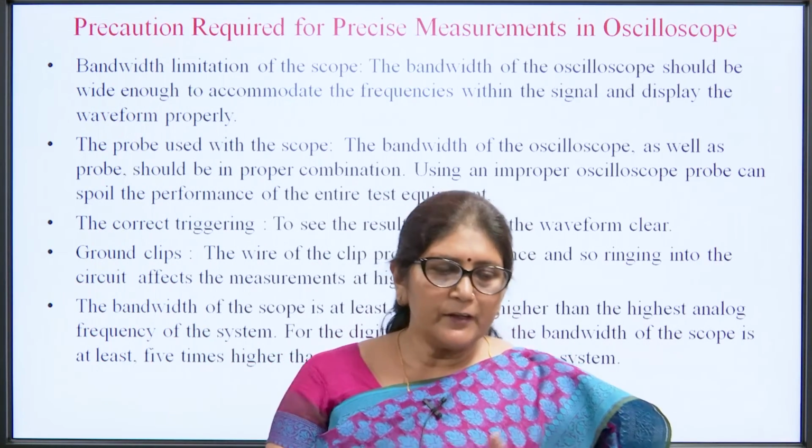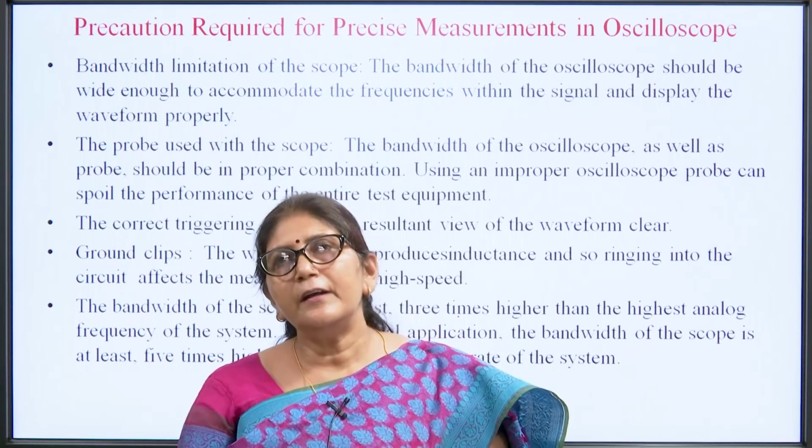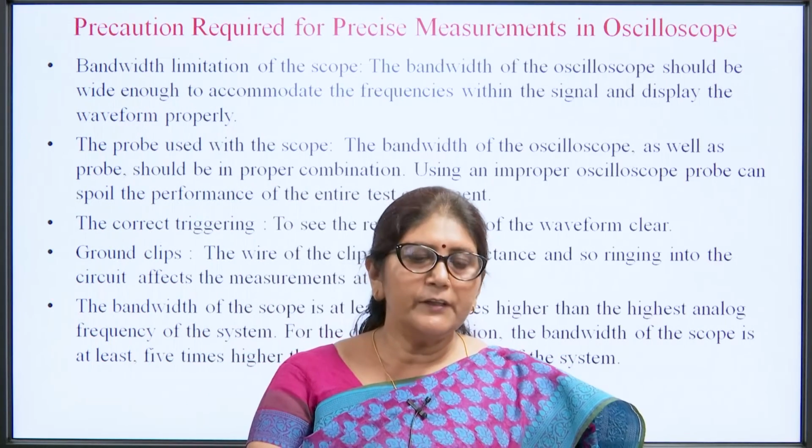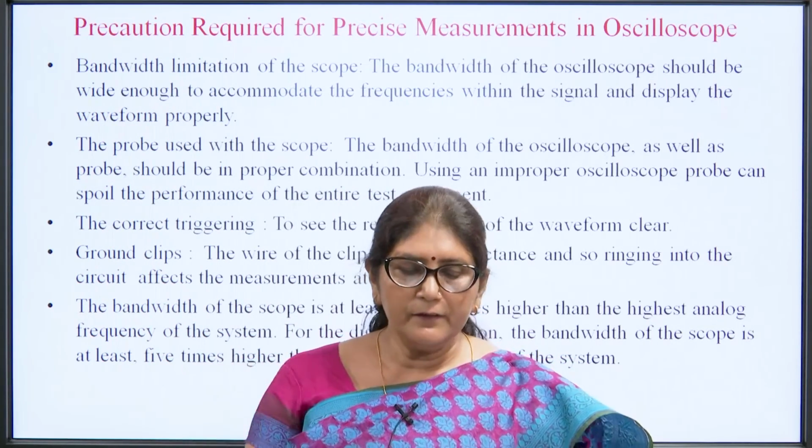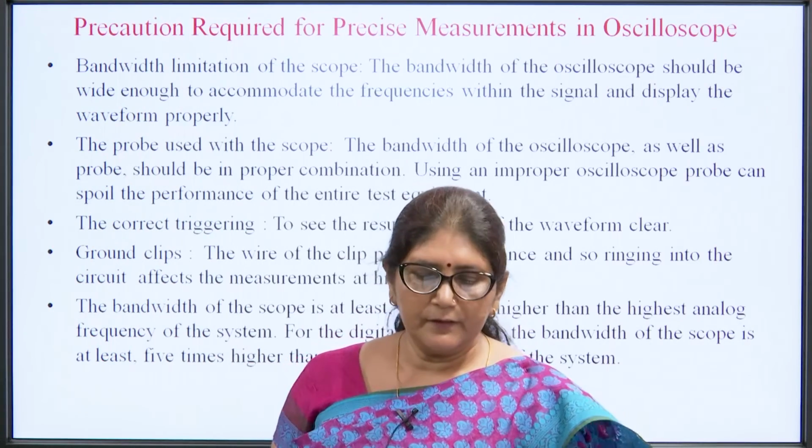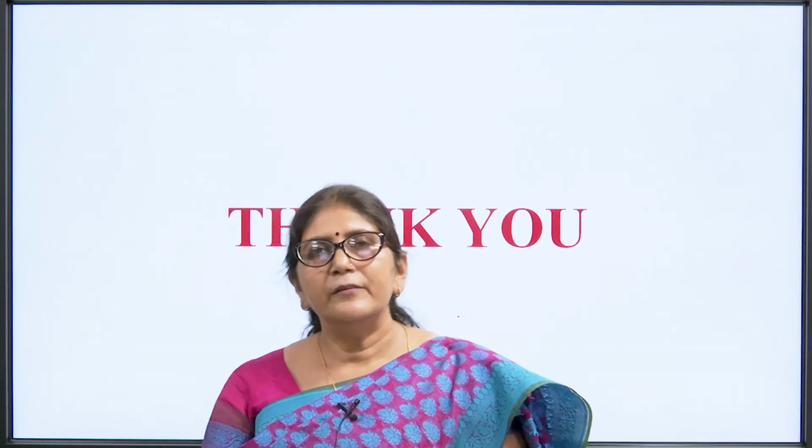Then bandwidth, as given here, should be 3 times higher than the highest frequency for an analog signal and at least 5 times higher for a digital signal. So, this is all from my side.